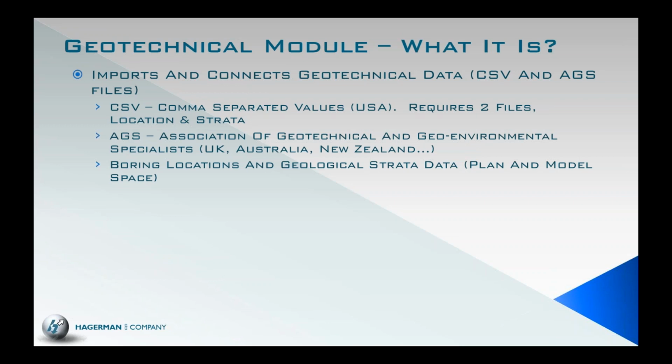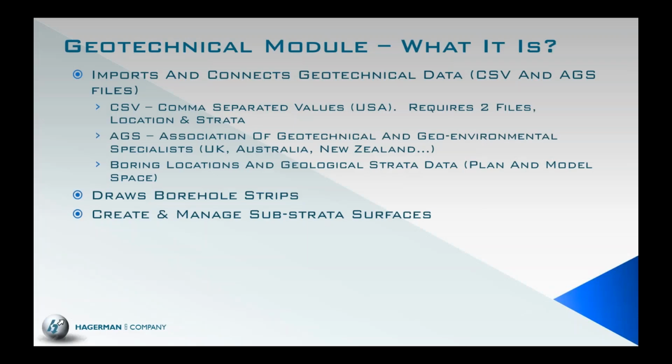And it also allows us to see boring locations and the three-dimensional strata data, okay? Whether it's topsoil, limestone, sand, what kind of information we have actually going on with our boreholes, okay? So we all know that prior to any type of, hopefully, construction and design, that we've sent out a crew, a geotechnical engineer. They're going to take the big boom out there. They're going to start drilling and pulling up plugs. So it'll tell us exactly what kind of soil we're going to be dealing with here on our site.